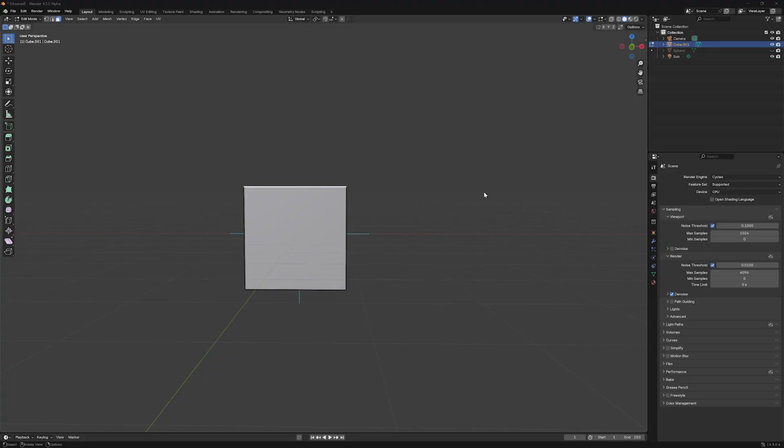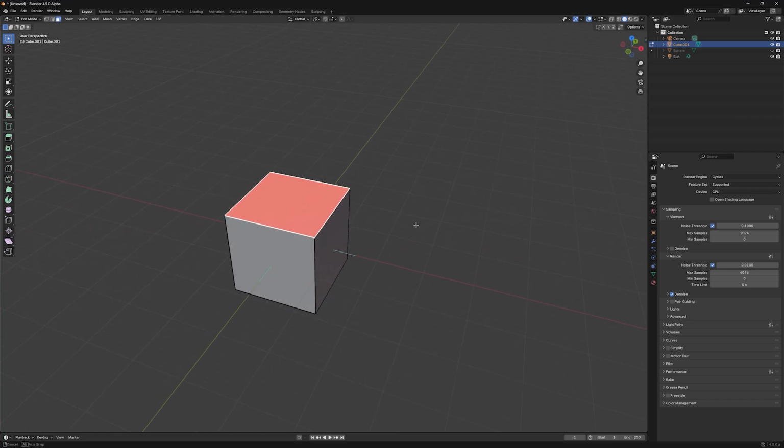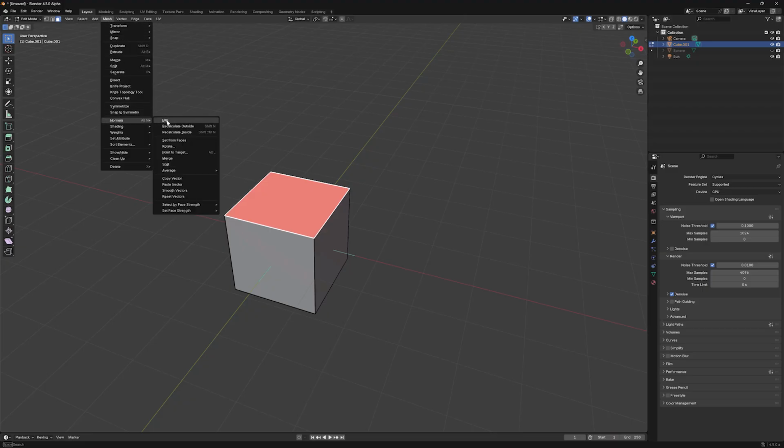The most likely is that as we edit a mesh, occasionally Blender will create a new face orientated in the wrong direction, with its back face pointing outwards. Since Blender doesn't do this often, we'll cheat and start with a cube where one face has been already flipped to the wrong orientation. Using the flip command on the wrongly orientated face corrects our problem.